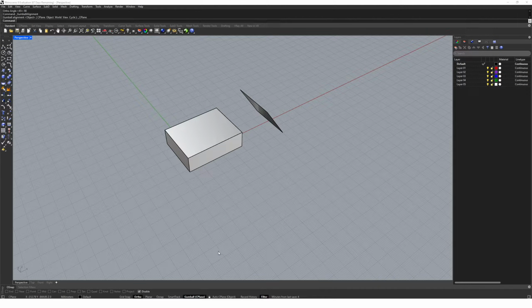One of the most critical features in Rhino that allows for accurate 3D modeling is the O-snap tools, which is a series of tools that let us snap our cursor to specific parts of geometries. Let's demonstrate a few of these. Our O-snaps live down on our bottom left. Let's enable these by unchecking disable.